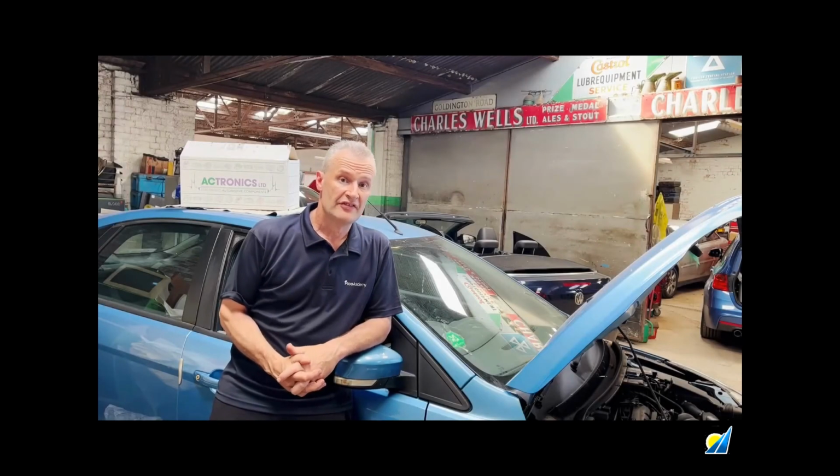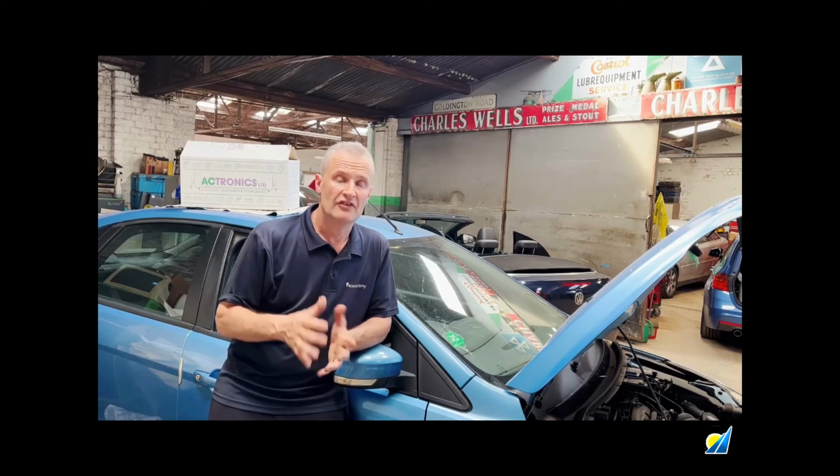So thanks to the team at AC Tronics, the instrument panel has come back, fully refurbished, and that leaves nothing really other than to do the resistance check first of all. You remember using the Pico resistance lead, how we tapped the instrument panel and we were changing the impedance of the network. At times it was 70 ohms, 80 ohms, occasionally 120, so a complete open circuit. And then we'll run CAN, so we'll start decoding in PicoScope, tap the instrument panel, try again, see if we can force this error, and monitor with Vehicle Spy as well, looking for CAN errors, receive error counts.